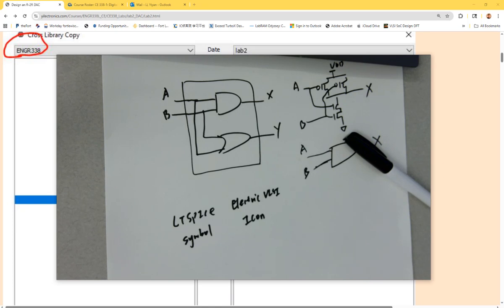Is it better to use the same design for all these spots, or to use different modules for the 1 million cases? It's probably the same for all of them, right? Because whenever you have issues in the circuit, you just fix the original module you created, and that fixes all of the instances being used in the circuit. That's another advantage of modular design.